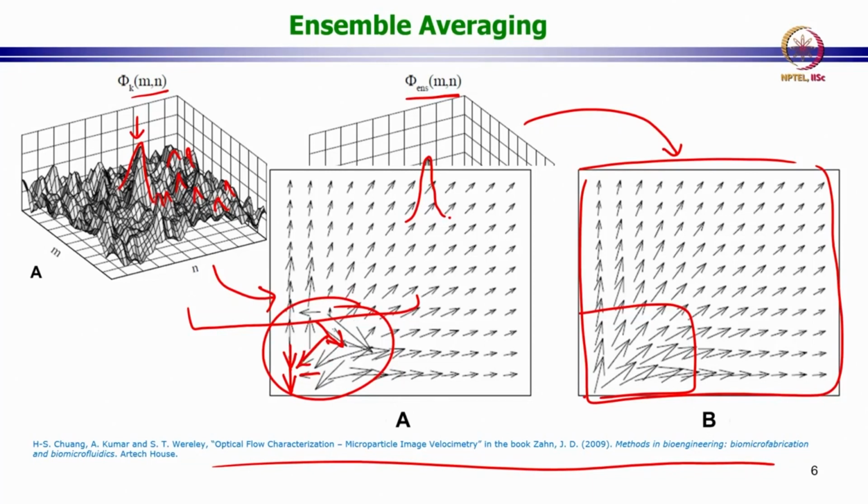In this case, you could see that the flow field looks very straightforward. It looks like there is a source type flow, something flowing out from this corner and going in different directions. But suddenly you have a line here which is very long. You also have flow reversal all of a sudden in this case, and these seem to be spurious vectors, right? So you want an algorithm which can detect this and replace them with correct vectors.